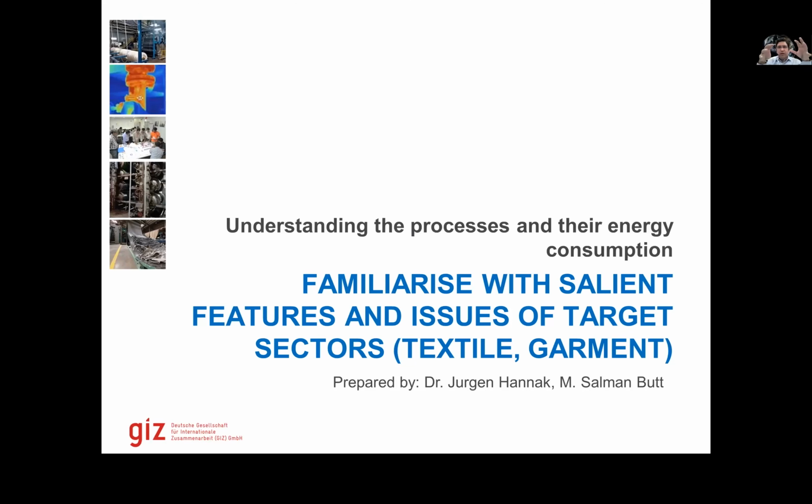So even if you are standing there in front of an alien machine, all you need to do as an energy auditor is to understand what different inputs are going in, especially the energy inputs, how this energy is being converted into useful work, how much of this energy is being carried forward by the product that we are producing, and how much energy is going out as waste. So to identify that, we must know where this energy is going.